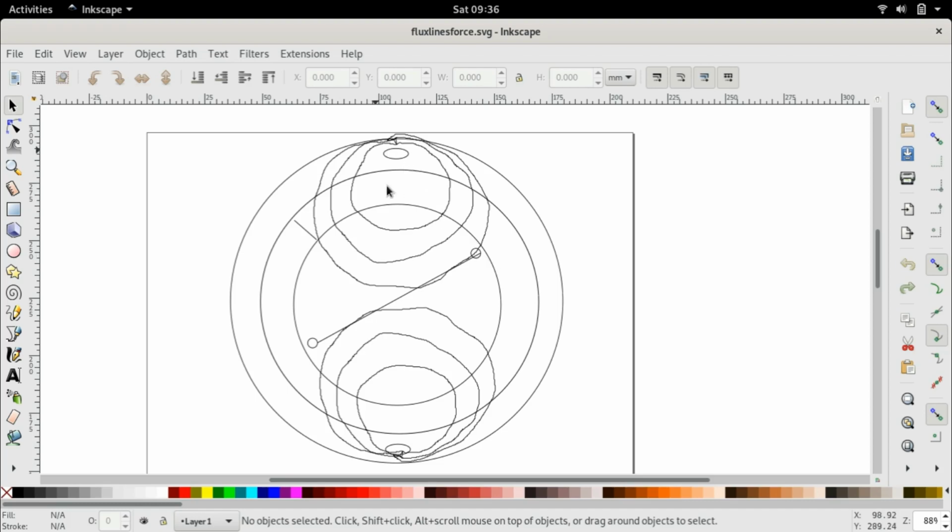And as you can see, the flux produced by the stator is associating with the rotor. So now an EMF is induced in the rotor, and because this is a squirrel cage induction motor which consists of bars short-circuited on both ends, a current will flow through the rotor because it's basically short-circuited bars. If you produce an EMF in a short-circuited system, a current will flow through it. Simple as that.